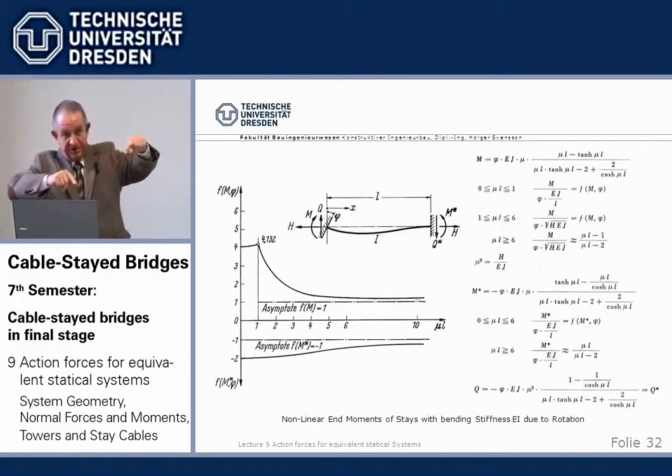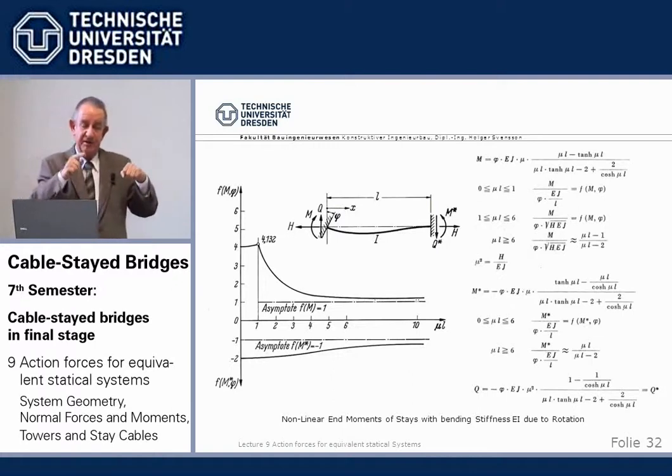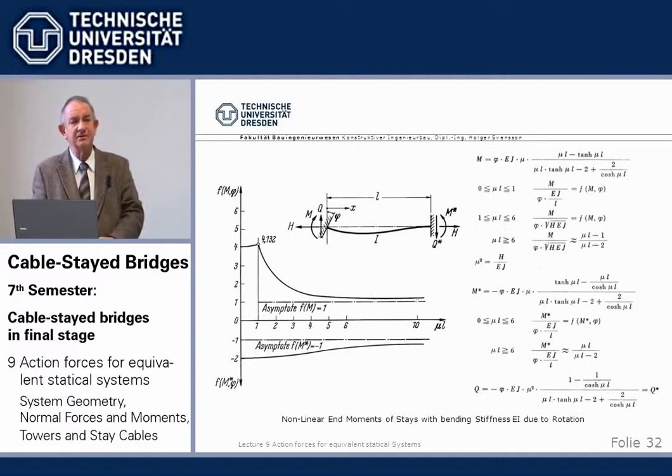It's pulled together there, and so the tension has a nonlinear effect of increasing the stresses, which is important for the sizing of the stay cables.